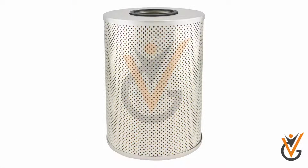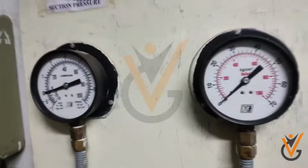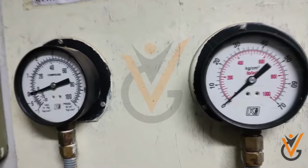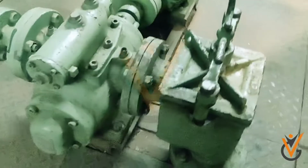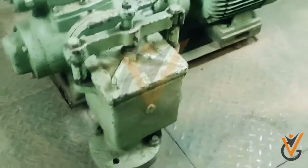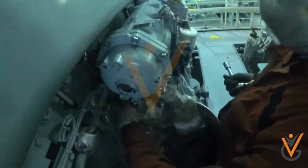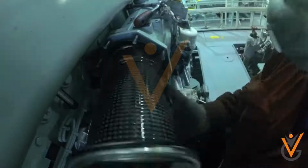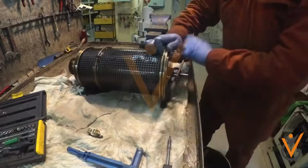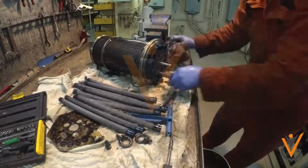Filter. The filter is a fine mesh screen which is used to remove impurities from oil, water, and air on the ship. The filter can be utilized both in low pressure, that is suction, and discharge, that is high pressure side of the system, and is used to remove the smallest part of dirt which is carried away in the system. The cleaning frequency of filters depends on the type of the filter and is decided by the manufacturer. The schedule is generally included in the planned maintenance system on board.